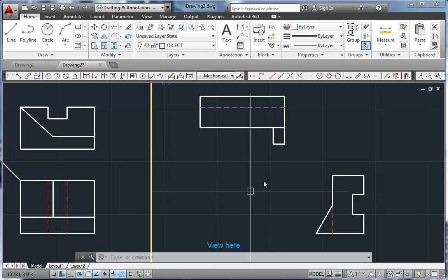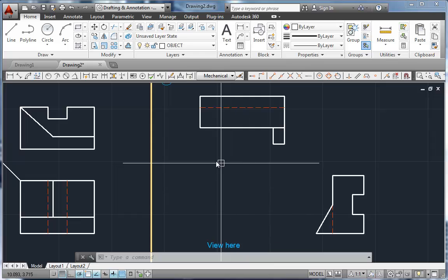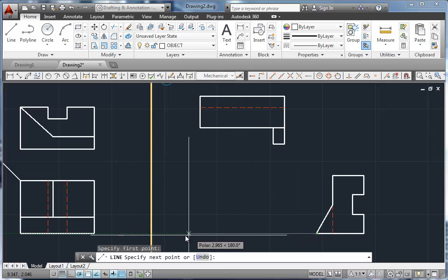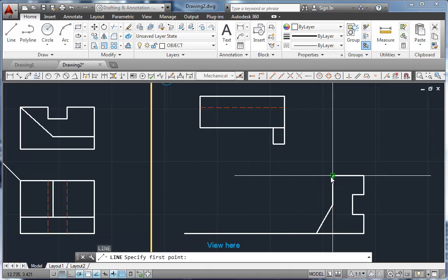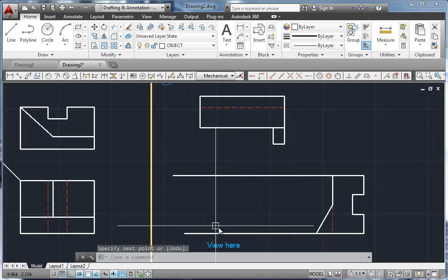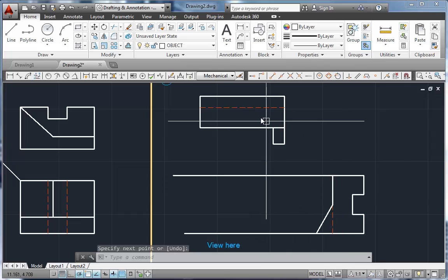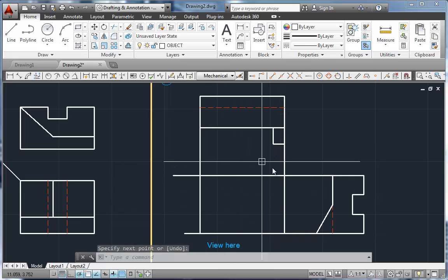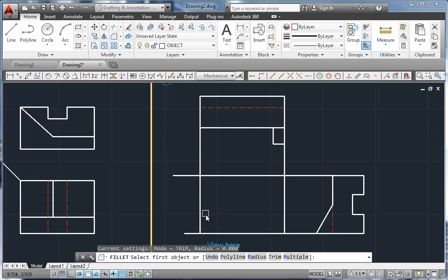And let's have a look at how that would happen. I'm going to start a line, and again, transmit my height. We're creating a front view now, so I have the right side and the top view. Everything just projects. There is no miter line. And there's my front view. I'm going to fill at those corners. That's the box or the envelope for my front view.